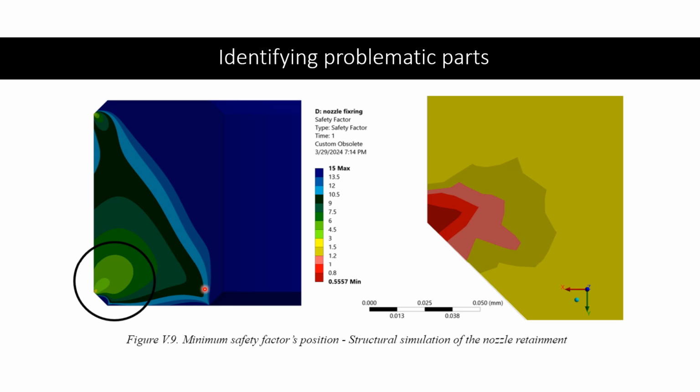When we define the boundary conditions, we define them on an edge or a surface, and it might be that one corner receives an enormous amount of stress, and due to this it kind of fails there. This is not good for the overall solution, but when our mesh is refined enough, it is almost impossible to see its effects on the other elements.